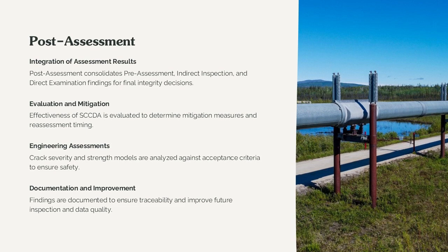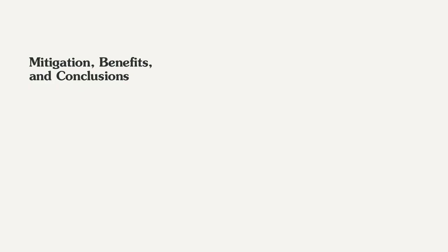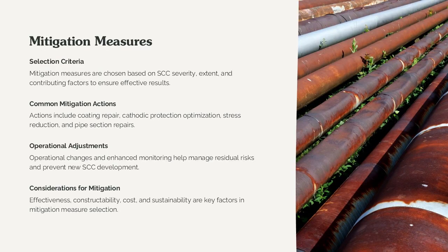By systematically documenting findings and decisions, this step ensures that SCCDA outcomes are traceable, auditable, and aligned with the operator's integrity management objectives. Mitigation measures, advantages of SCCDA, limitations of SCCDA. Conclusion. Mitigation measures following SCCDA are selected based on the severity and extent of SCC, as well as the underlying